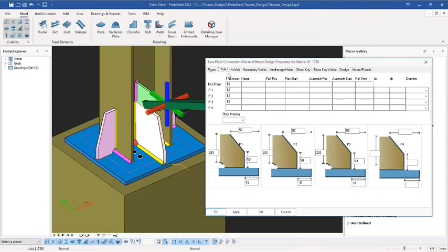Alright, so go back to these provisions. You can see the height of this stiffener now is 200 millimeters. Alright, so we also have the chamfer to be 50 by the height, and then by the length you have it to be 50. But for this one, because this stiffener is the one at the center or the width of the stanchion, we always make that 100. Okay, just like this. If I click on apply now, you can see the changes right there successfully.